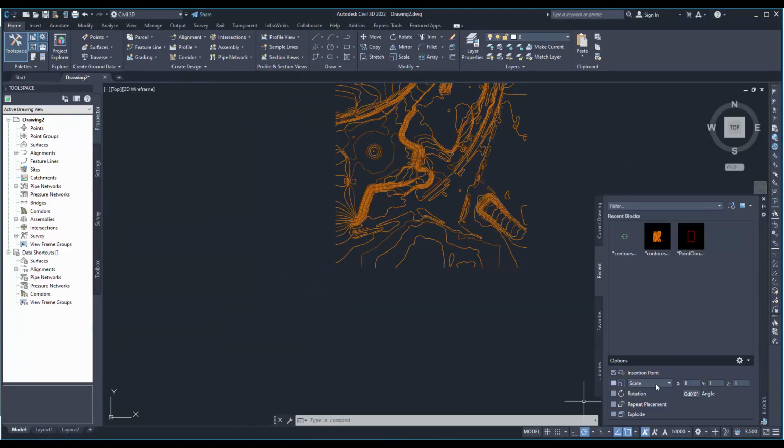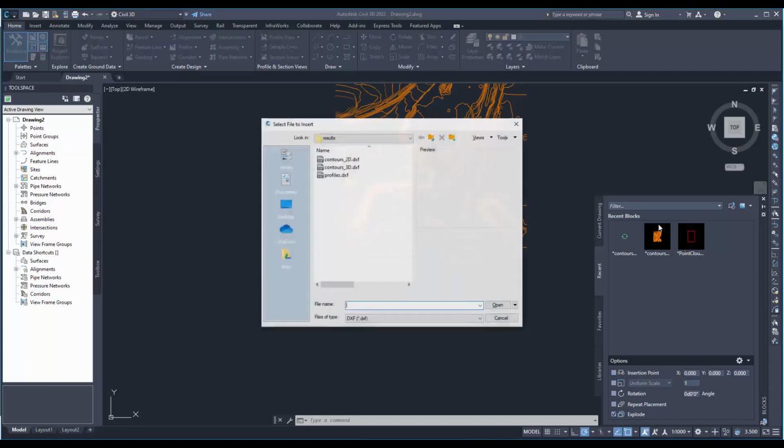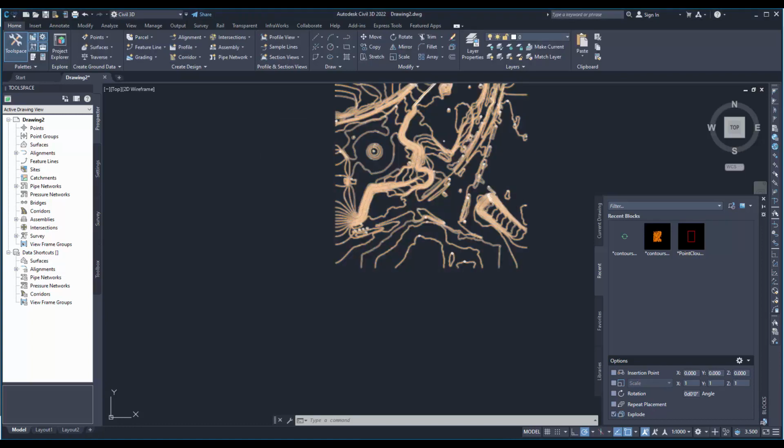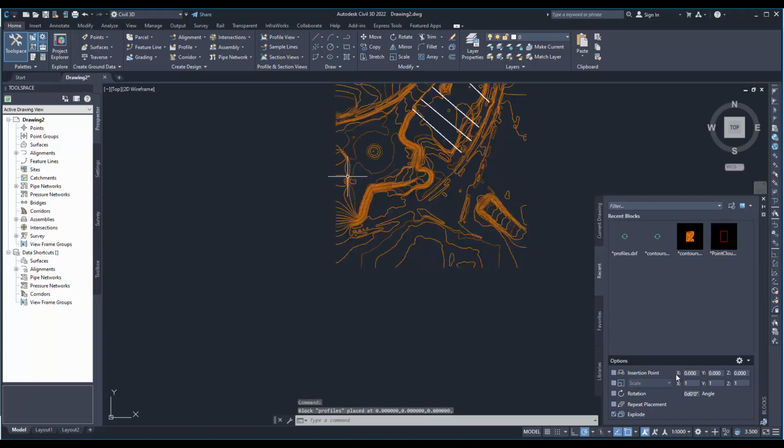If we bring that one in here into AutoCAD, so this time we can set insertion point will be at 0, 0, 0, scale 1, rotation like that. Let's keep it, let's explode also that part. Bring in that DXF. Now we specified the insertion point here.